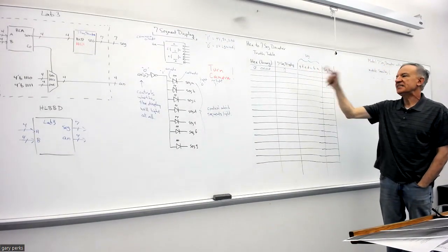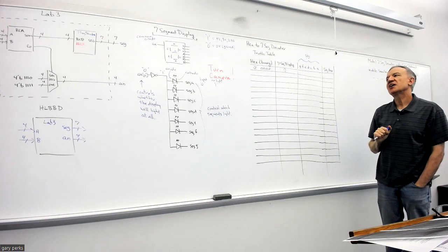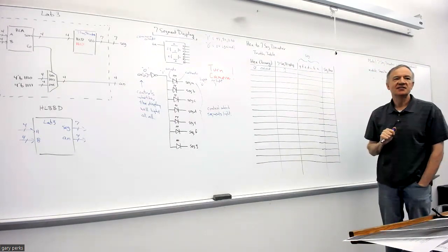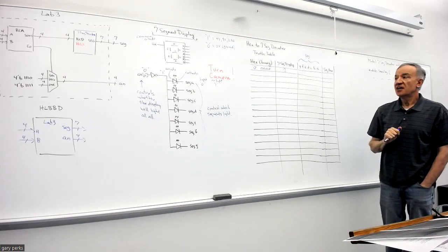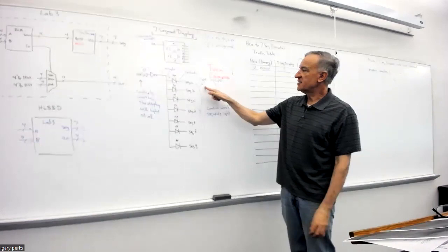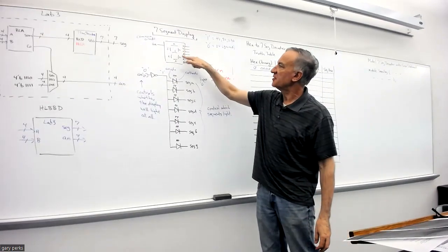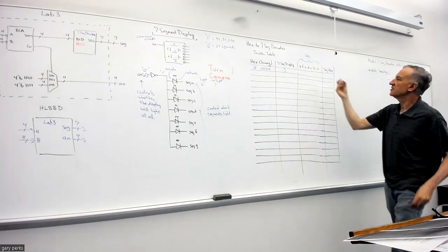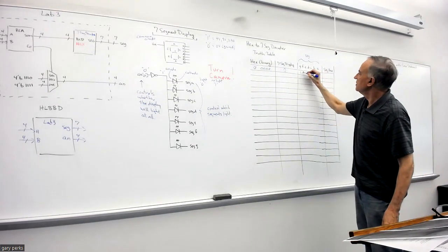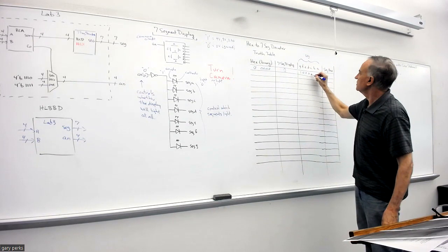If I want a 0 to show up on that 7-segment display, which cathodes do I want to be 0 and which a 1? A through F should be zeros, because remember, it takes a 0 to light a segment. So only the G segment would be a 1. You just write 1 0 0 0 0 0 0.